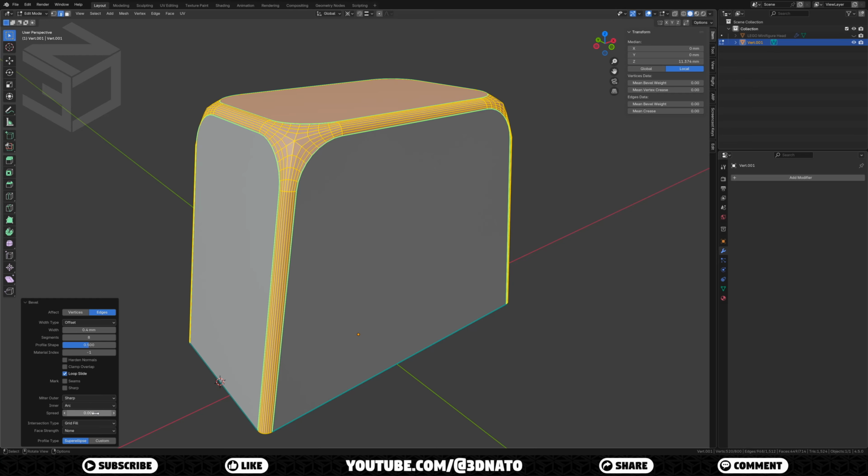This part here took me a lot of tries to achieve the result I wanted. I've tried to mess with the bevel segments, but always got this weird pointy corner. Then I've tried to use Relax from the Loop Tools add-on, but it turns out even worse. The way I found to fix this is not perfect, but it was the best result I got. If anyone knows a better way to fix this, leave it in the comments so others can see.